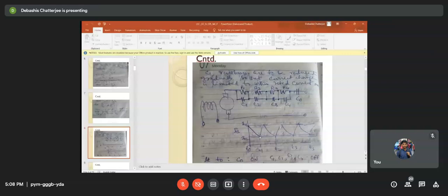Now you change the next resistance, so you reduce R1 here. Now the current will again rise to this value with the next resistance, and again it will reduce because the speed is increasing, right? This way your current plot will be formed.